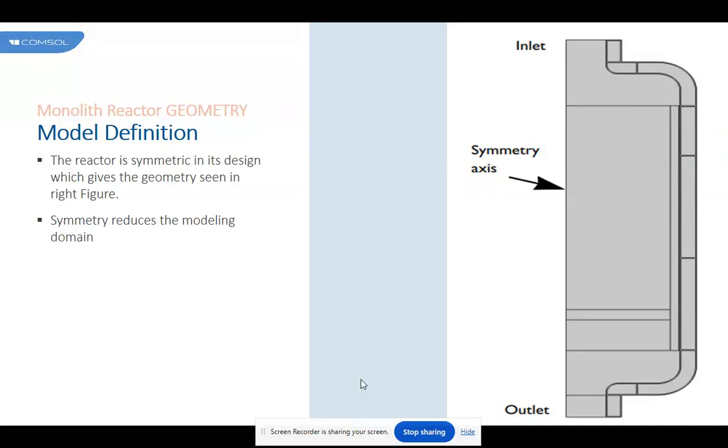Another way to speed up the calculations, also used in this model, is to use Generate Material from Thermodynamics. Information about how to efficiently use the thermodynamics feature is available in "Using Thermodynamic Properties". The system conditions used in this model are the same as those in the single channel plug flow system that describes the analysis of nitric oxide and ammonia conversion kinetics in a dual-bed plug flow reactor. Three engine load cases are investigated with a fixed ammonia to nitrogen oxide ratio, and the three engine load cases result in the following inlet gas conditions.